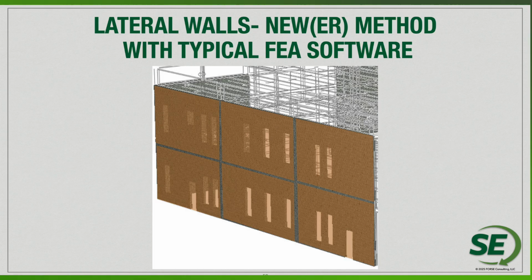So again, this is going to take finite element analysis software to really understand and appreciate what the forces are between those lintel areas, those areas above the openings, to the jamb areas on each side of the openings, to the area below windows, or just how those different elements are going to be connected to the foundation. There is quite a bit of complexity in those plate elements that we have to account for, and so certainly utilizing the right tools for our shear wall analysis and design would be necessary.